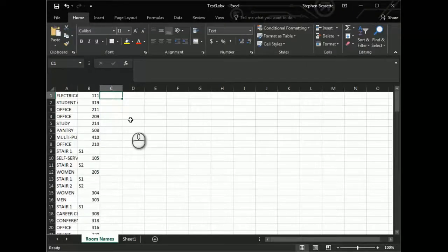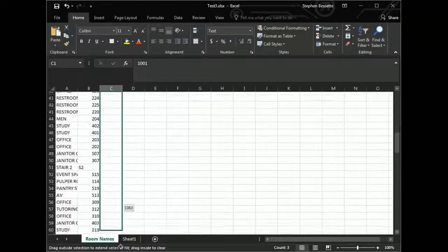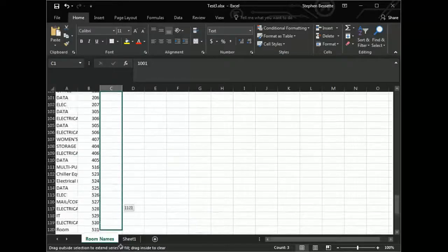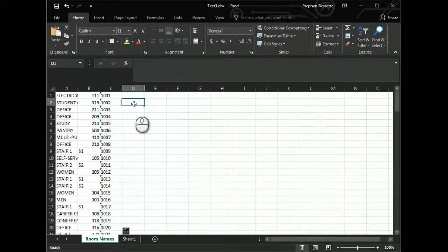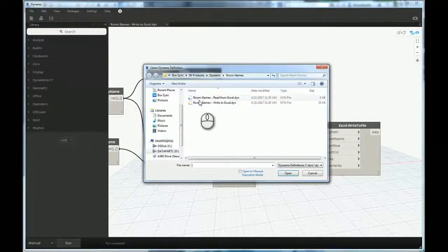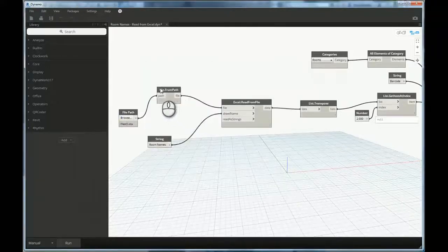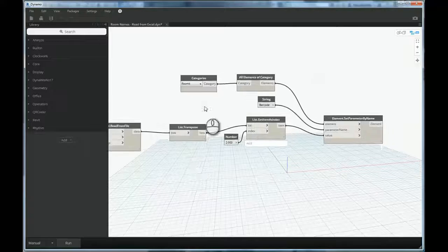124 some odd rooms in this building. I don't want to have to input every single four-character barcode in here. I'm going to do what we've always done in Excel. Put in a couple of numbers and drag and drop. Generate it all down, and then after the fact, you're just tying it back to that model database. You're just a couple of clicks and you're in. And the thing about a script like this is it's not based upon specific objects. I could do it against furniture, doors and doorknobs, whatever category or family type I can attach this to.